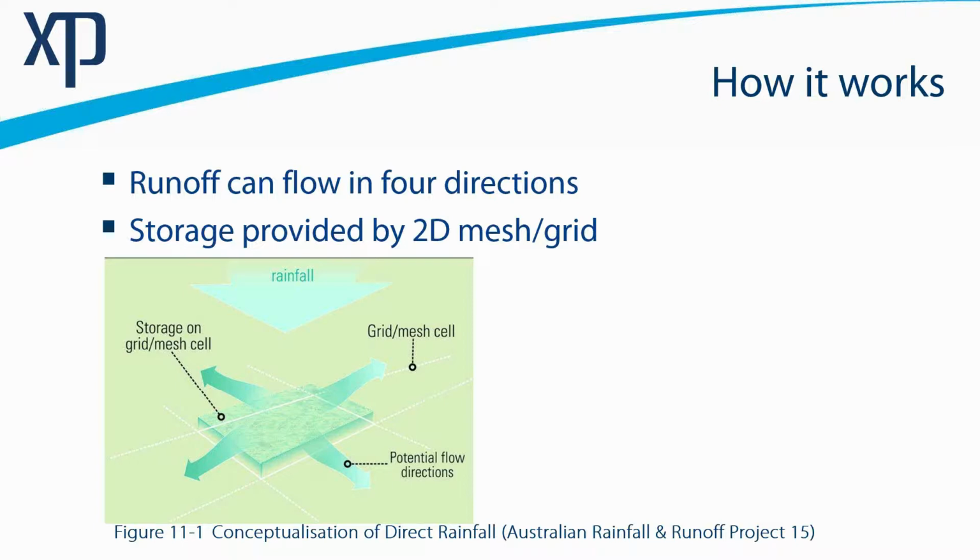We're using the full 2D equations. We're not using 1D equations. So once the water hits the deeper parts of your model, starts to move down your rivers and creeks and so forth, you will be modeling all the terms of inertia and eddy viscosity. So it's a very seamless transition. There's the same equations being applied whether you're up in the hills or down on the floodplain.